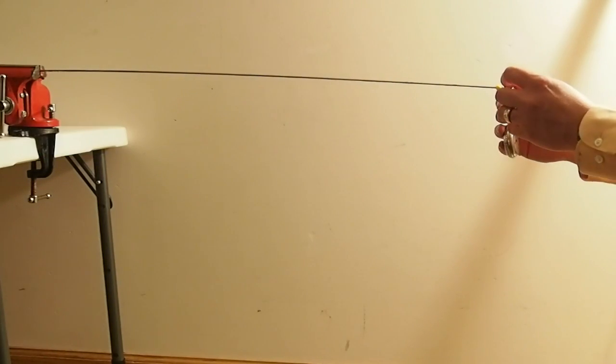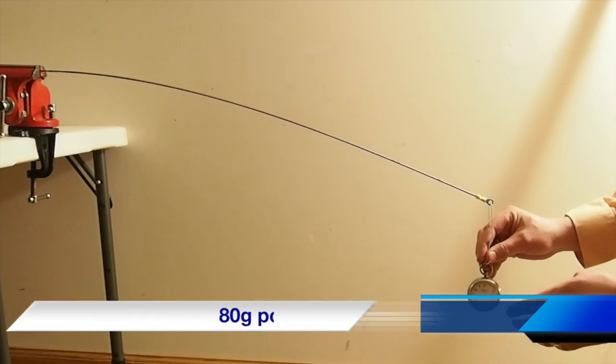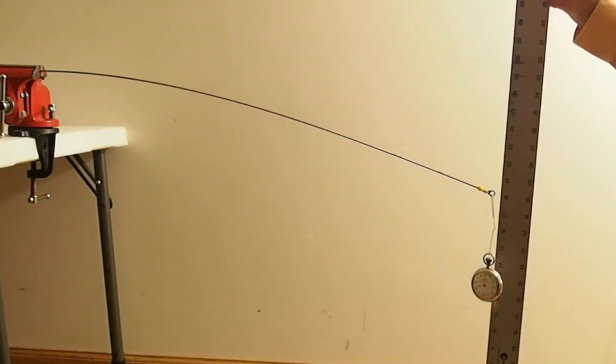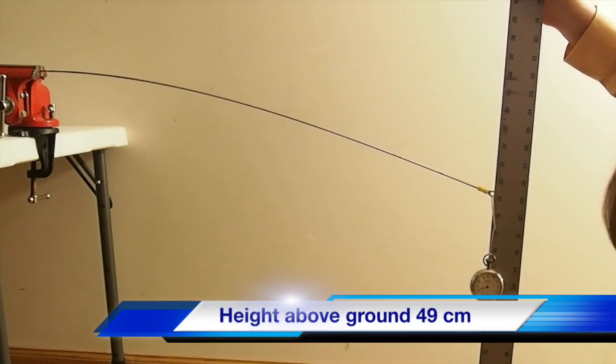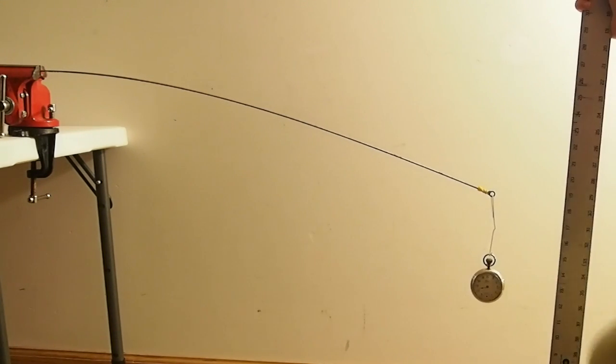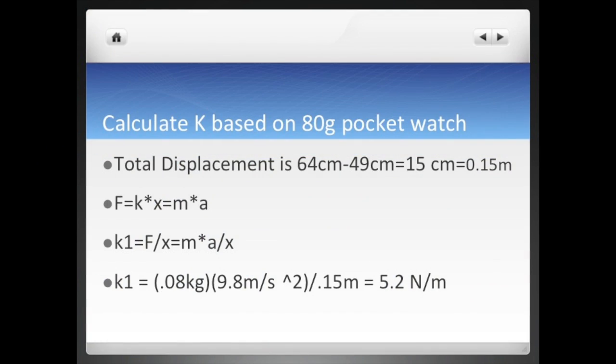Then take a pocket watch, which weighs about 80 grams, hang it on the rod, and measure the deflection above ground to be about 49 centimeters. Taking these numbers and plugging them into the equations, net deflection of 15 centimeters with a mass of 80 grams and acceleration due to gravity gives us a spring constant of about 5.2 newtons per meter.